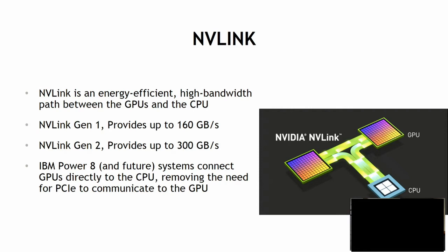A couple of questions. So, are there any counters available to measure the amount of traffic going on the NVLink, like as part of the NVIDIA performance counter suite? So the question is, are there counters available on the NVLink to monitor traffic? Yes. Yesterday I showed some ways with the NVML library that you can pull some counters, at least for transfer rates. You can get counts of bits going in both directions. Second question is, can we measure the amount of power being used by NVLink to transfer it? Have the counters for that? I haven't seen those.